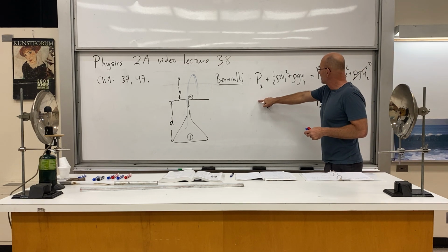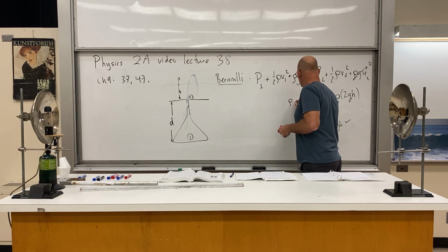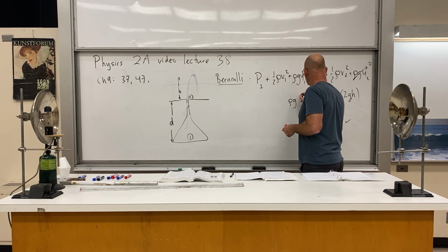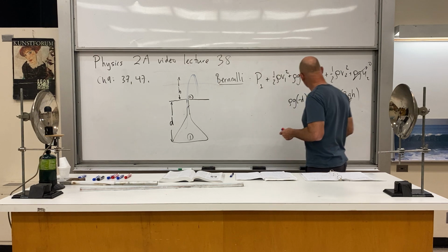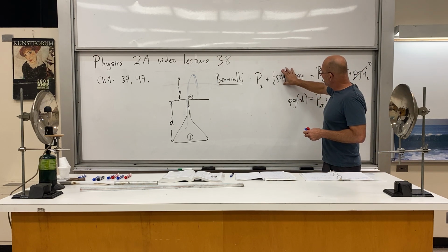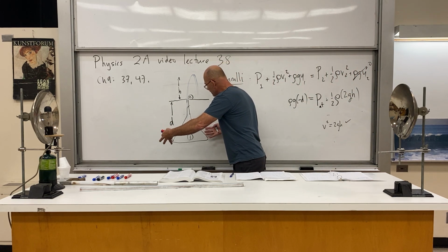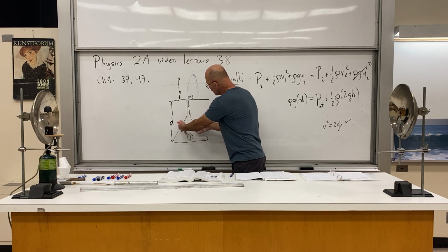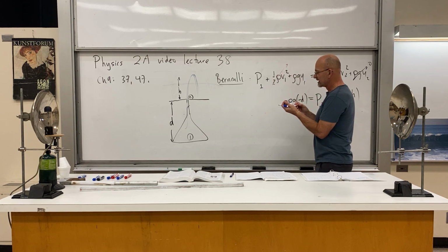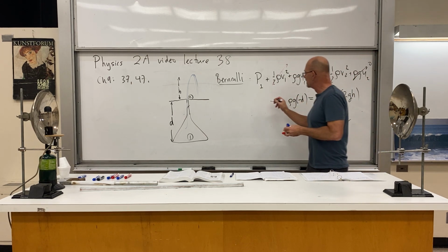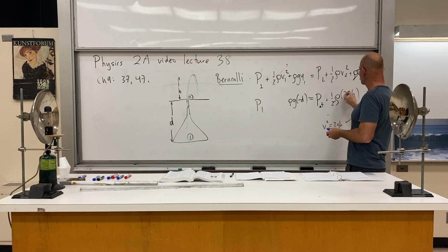The left side, we're going to have rho g minus d, because we're down here at this great depth in that cavern down there. We're going to say the V sub 1 is negligible, similar to the prior problem, because it's the motion of the fluid down here, down low in the large area. So this is negligible again, and we can ditch that. And now we're going to get P sub 1, and I'll solve for it. Okay, we're actually done.